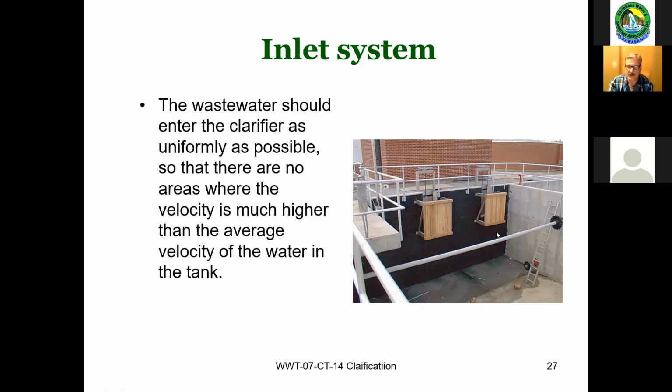So you have a primary clarifier functioning at this end of the tank. It starts to function, rather than if you didn't have those baffles, there's quite a possibility the primary clarifier isn't going to function properly until the flow subsides a little bit from the influent, and then starts doing what it needs to do.